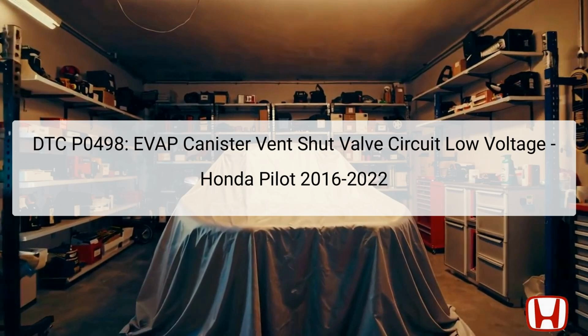The vent shut valve is typically located near the fuel tank or within the storage canister and operates as a means of controlling airflow during the evaporation process. When this valve malfunctions, it can compromise the entire EVAP system's performance, potentially leading to increased emissions and failing emissions tests. Understanding this code's implications is a vital first step in effective troubleshooting and repair.